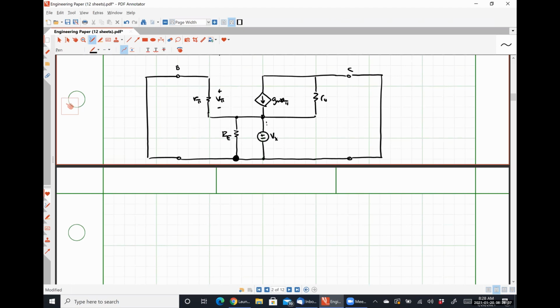So here is Vx, and here is my current of interest, Ix. And there's another situation where redrawing things is going to make this a lot easier to determine what's going on. So here's my voltage Vx, here's my current Ix. This is my emitter. Down here is both my base and collector terminals because they're shorted together. So in parallel with that, I see RE.